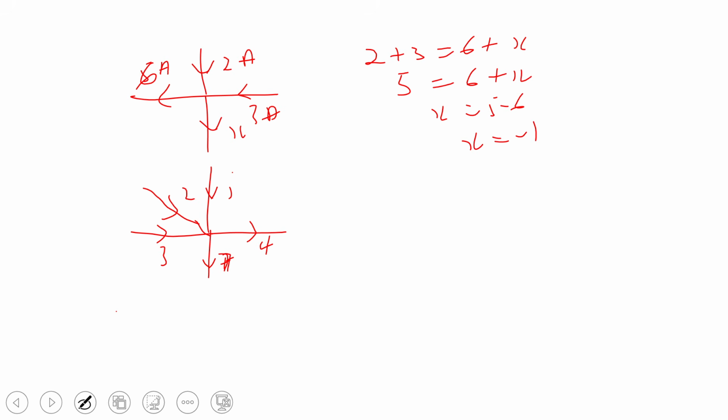So we have to look at I is entering the junction, this 2 is also entering the junction. We can see that 3 is also entering the junction, but then 4 and 7 are leaving the junction. They be at one side, so I will be plus, here is 5 and here is 11, so I will be equal to 11 minus 5, and that will be 6 amps.